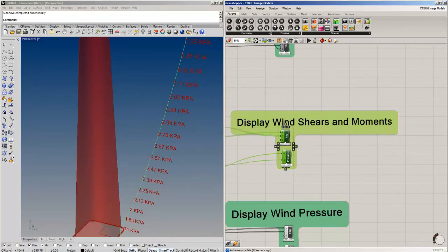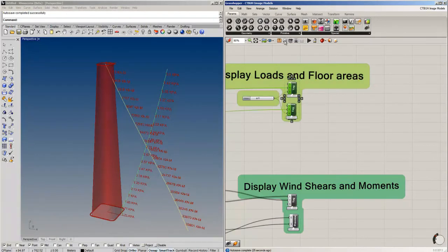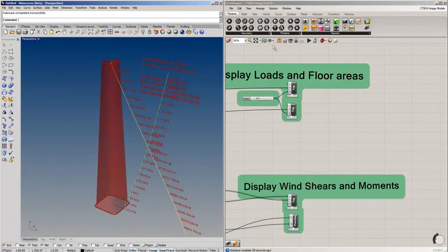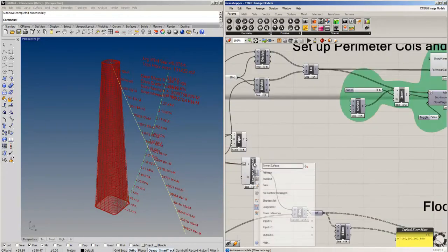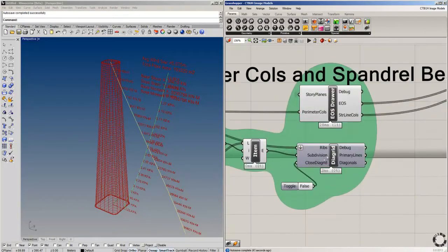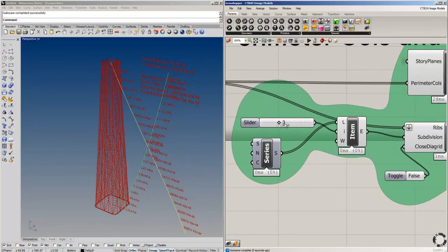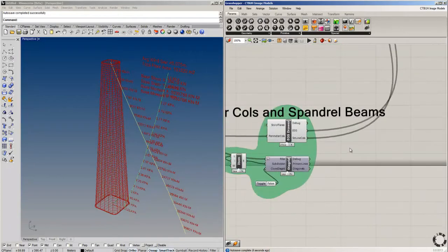So how do we go from being able to do very quick structural analysis and verification? The question this year is what's next after you are able to do something like this? There's an example tower where we can plot out the wind pressures, the base moments and shears on the design surface itself. We can naturally layer on structural information such as the bracing or perimeter beam scheme.